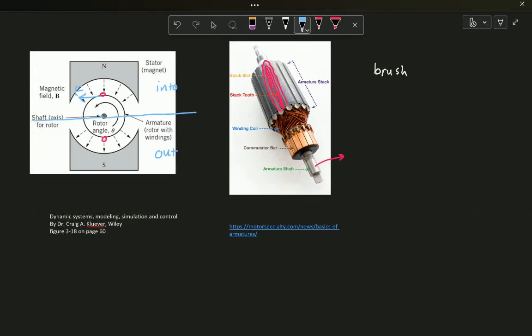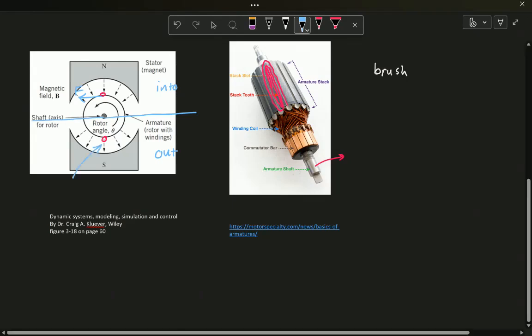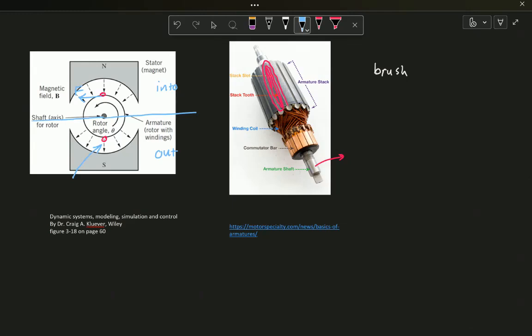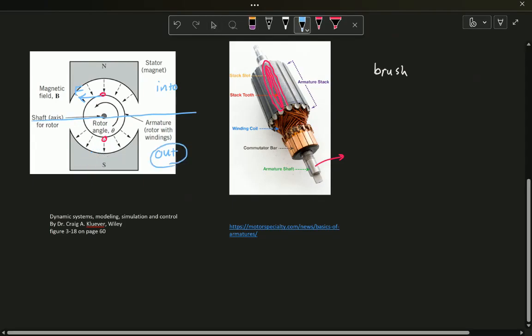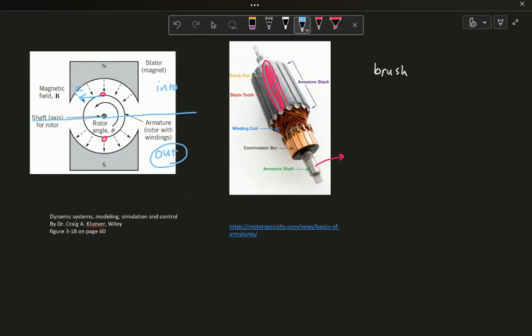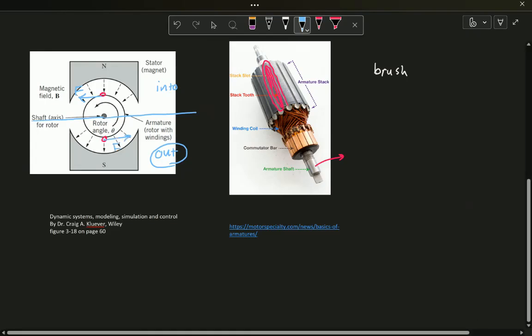Similarly, if you look at the wire on the second half of the picture, for this one, since the current is applied out of this plane, I put my four fingers in the direction of the current, I close my four fingers in the direction of the magnetic field, and my thumb shows the direction of the force.